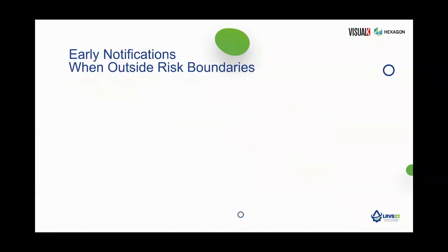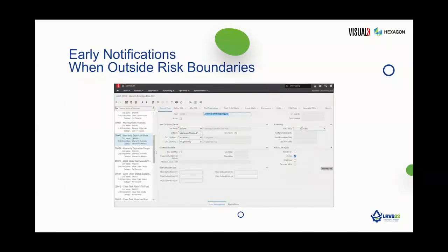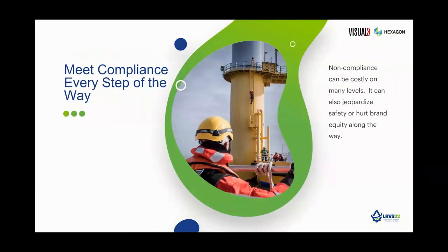For example, bring data from your SCADA, from your control system, put boundaries in place and have the system monitor where the asset is performing. When approaching those limits, notify. Obviously, if it exceeds the limits, then notify and create a corrective action. So the tools are out there.